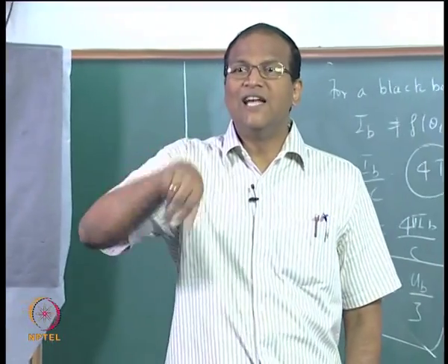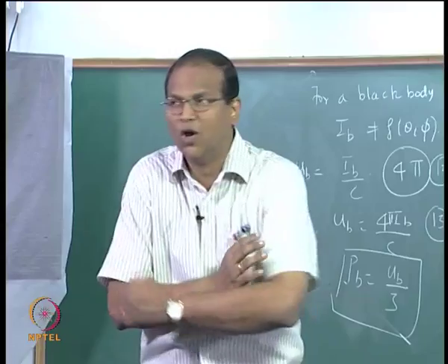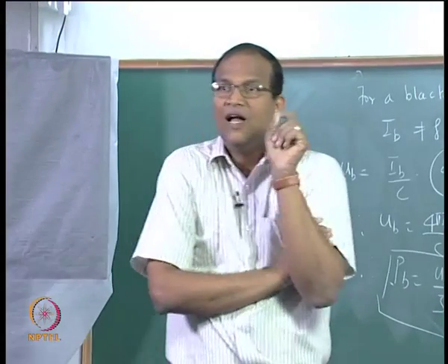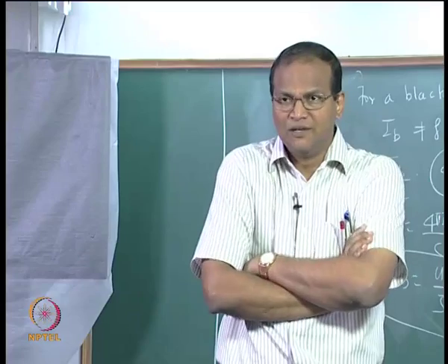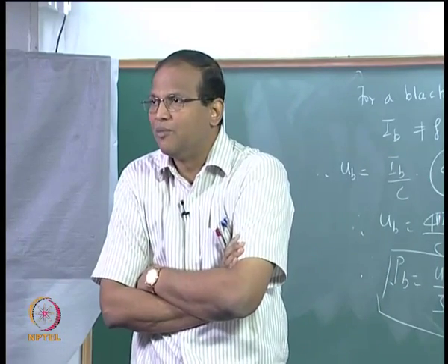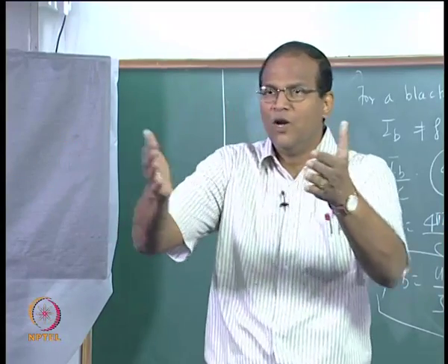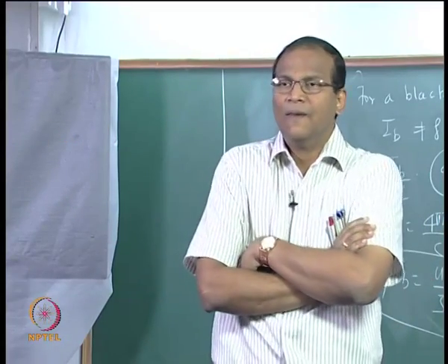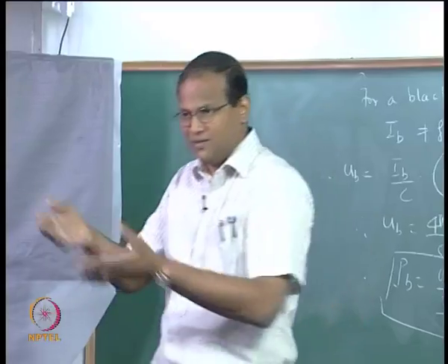Now I will say that radiation is assumed to be a gas which is having a temperature corresponding to a volume V, and therefore all the thermodynamic laws are applicable, and if I have the TdS relationship, then dS must be an exact differential because entropy is a property. Therefore, suppose you have an expression dz equal to M dx plus N dy, dou M by dou y is equal to dou N by dou x.